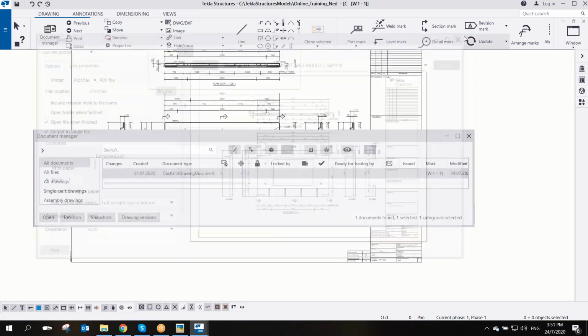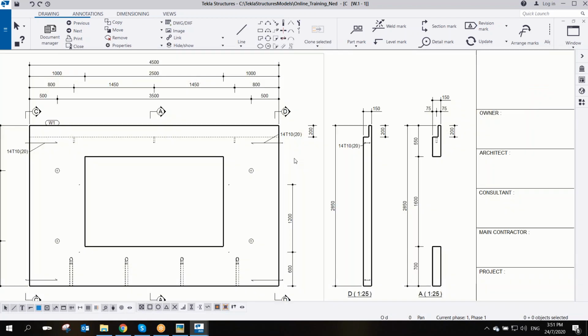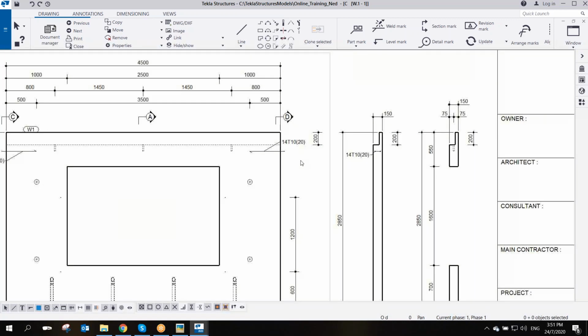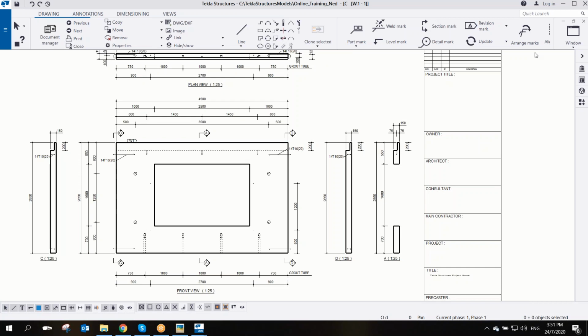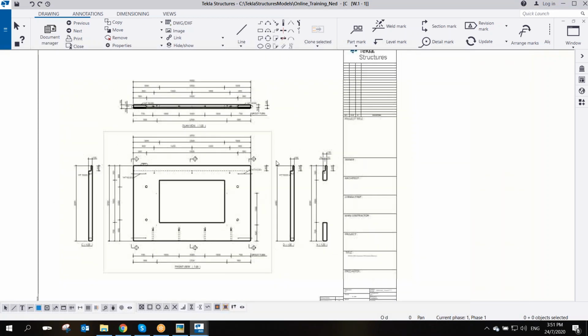But when I open the drawing, this one must be the outcome of your print. So it should be on the line assignment or the pen assignment. I hope, Howard, I hope I answered your question here. Yes, you need to select the color that is associated with the dim line here, and then you need to change the pen assignment. Yes, correct, that's right. So you have to set up your own pen assignment here.